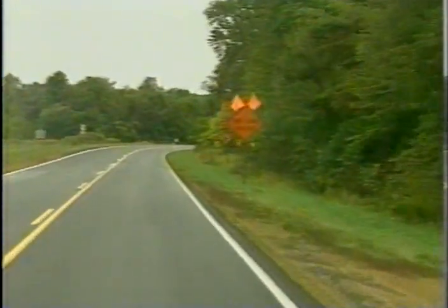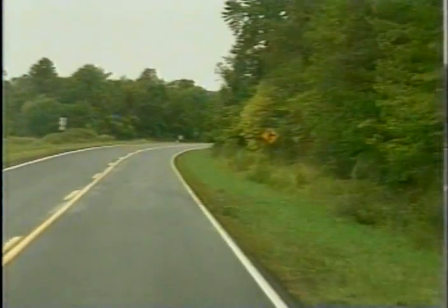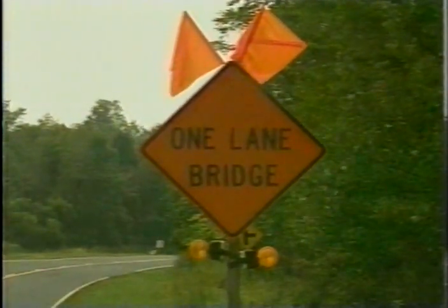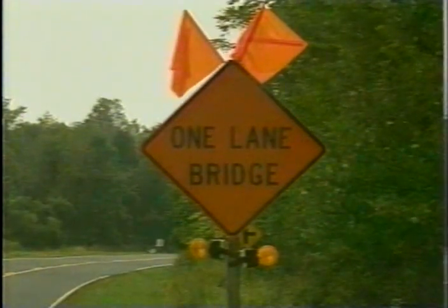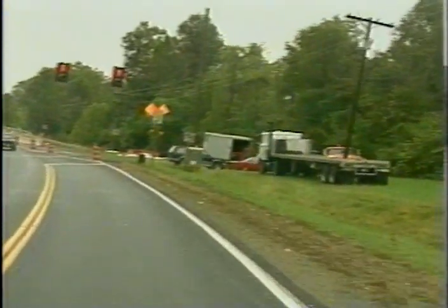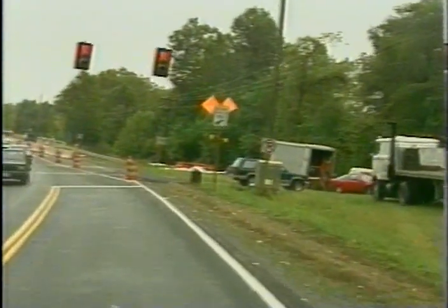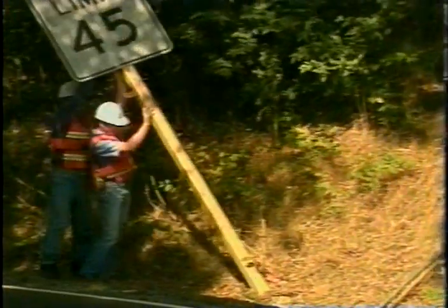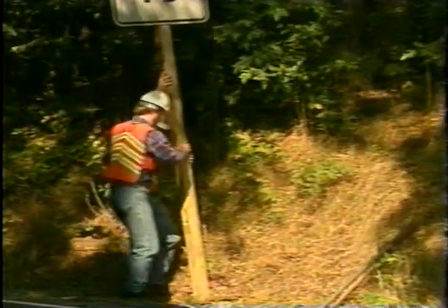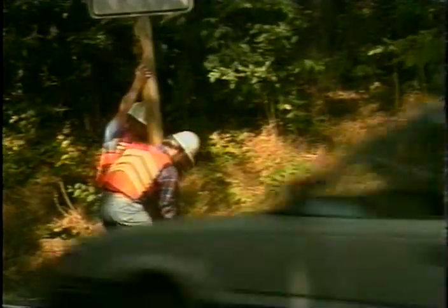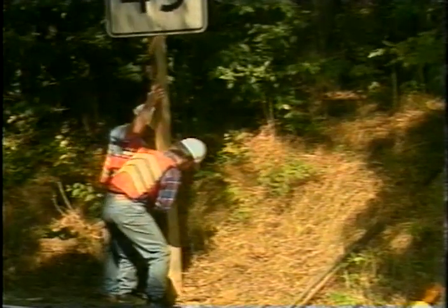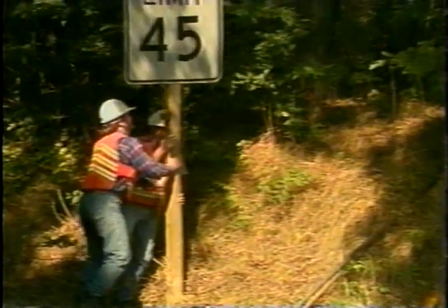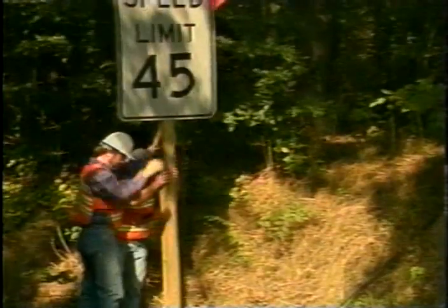which relates to the third principle. Provide clear and positive guidance for drivers in the approach area and as they go through the construction and maintenance work area. To do this, first install temporary devices to maintain guidance while permanent signs are missing. This will protect workers during the operation.